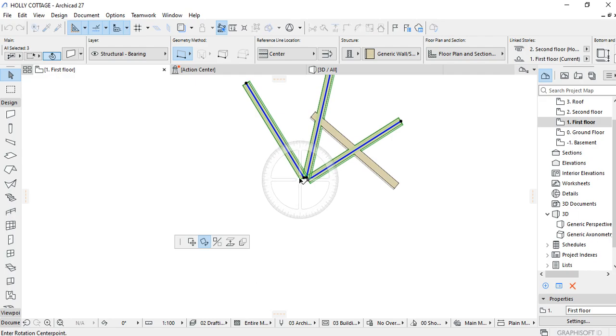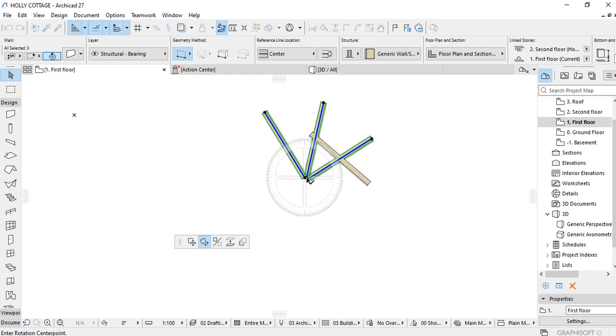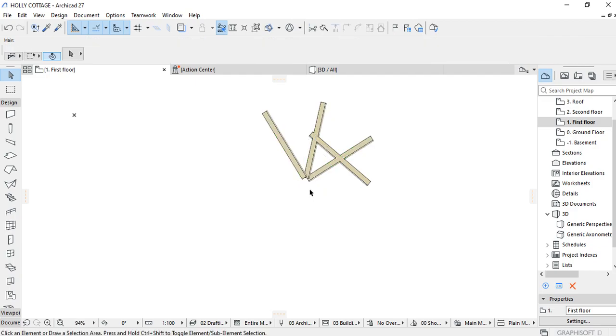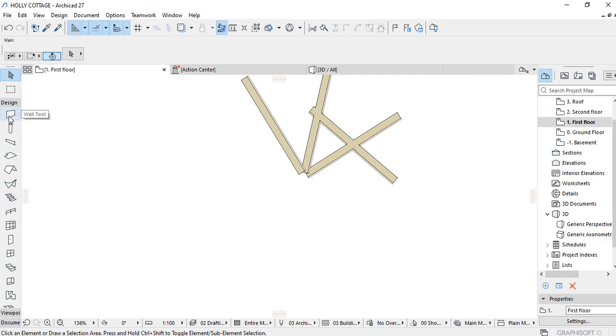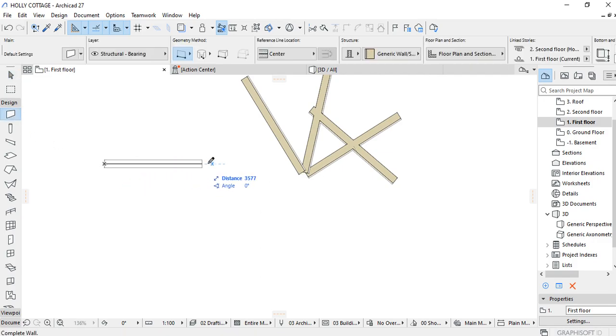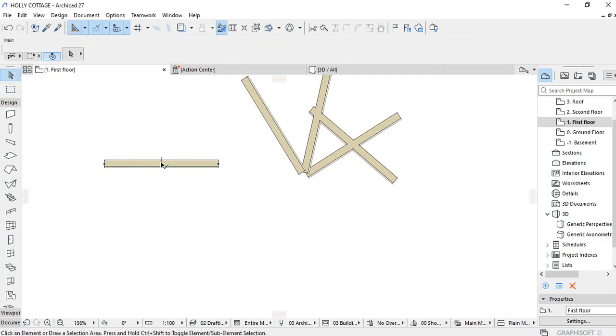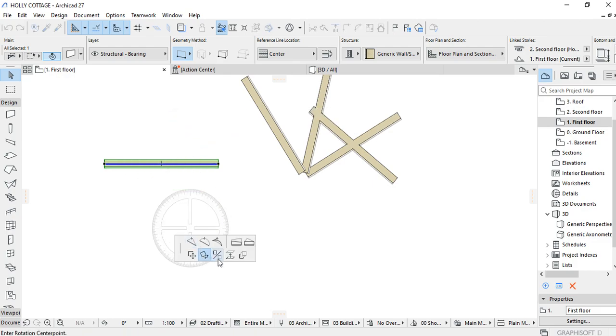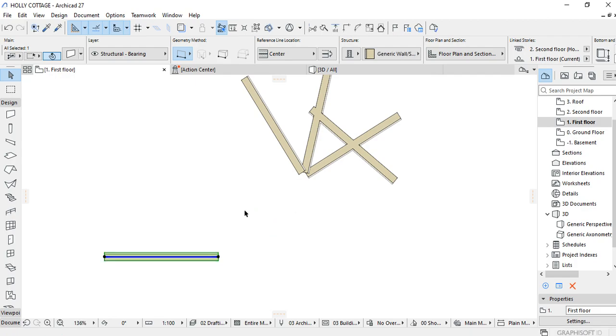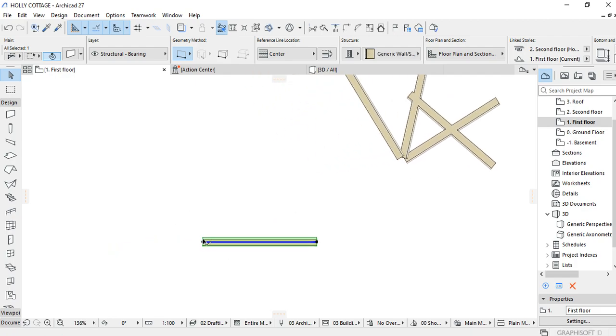In order to create multiple copies of the rotation. So the other command is the mirror command. If you draw your hole here, then you select it, then you right click, there is a mirror command here. After drawing the mirror, you can go to any point and draw the mirror axis. When you draw the mirror axis, it's able to mirror. So again, selecting it, choosing the mirror